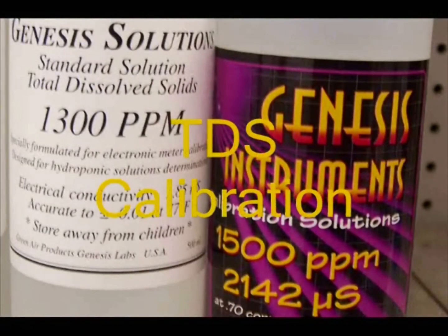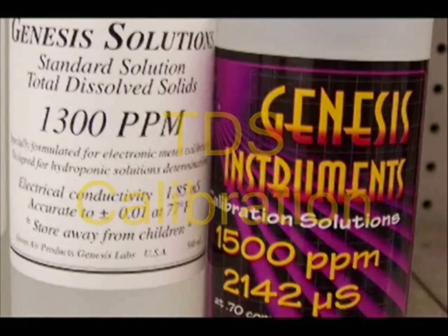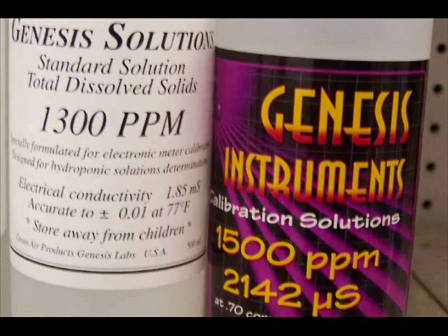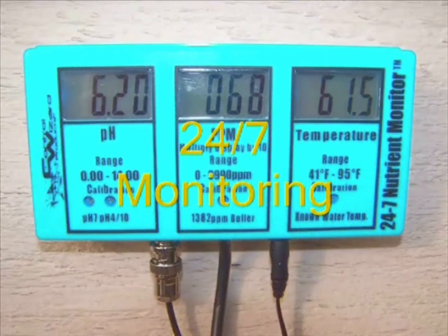The TDS pen is calibrated similar to the pH pen. Simply submerge the test probes in the calibration solution and adjust. Remember to always rinse the electrodes with distilled water after calibration.